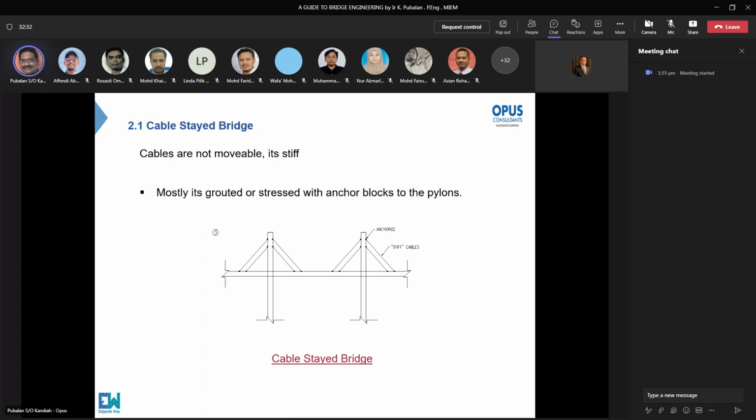Because as the pylon goes up, and the height of the cables increases, there will be wind action on top of it, wind and rain. So if you have stiff cables, then you need to do the analysis for stiffness. So your material inside has to provide that. And the other reason is that when you have unbonded cables, you have room for replacing each strand in the future. Whereas if you have already concreted those cables, you can't replace any of the strands.